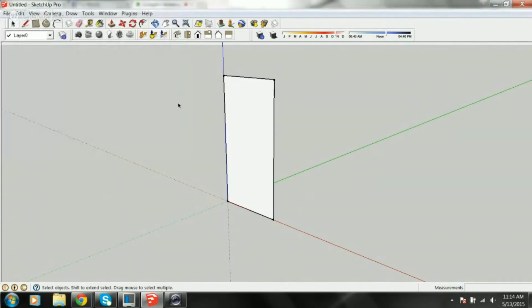Okay. So now, the first thing that I like to explain to people when they're new to SketchUp, or even some that have a little bit of experience, if you've never worked in groups, you've got to start working with groups. And in this particular model, what you're really looking at is probably a masonry group, like the main facade, a cornice group for that top parapet cornice that we're going to work with, and then maybe a windows and maybe a doors and maybe a lights. If you set everything up as groups, then you can individually edit them without affecting other pieces.